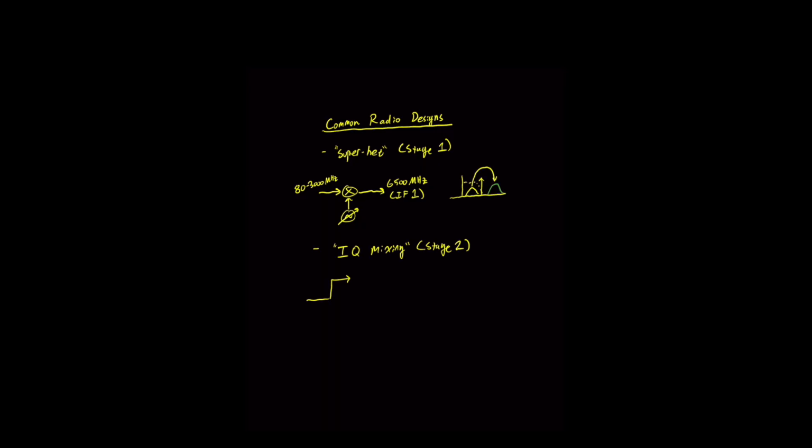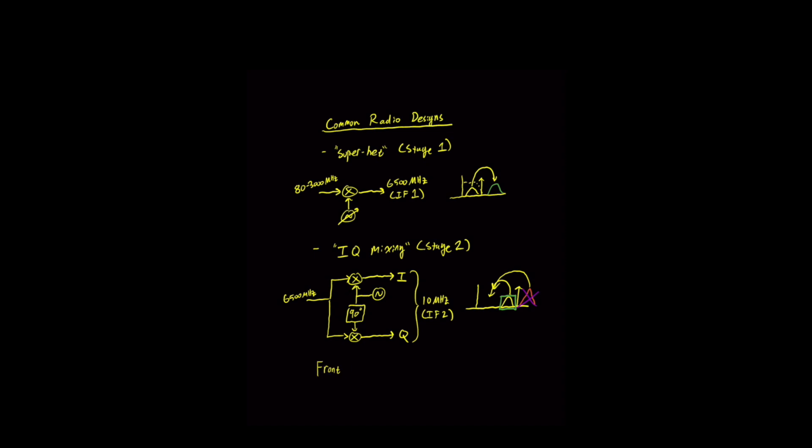Our RF design approach uses a combination of common radio designs to achieve our desired operational range. The final design is a combination of a superheterodyne radio that uses a second mixing stage for in-phase and quadrature digital signal processing to reject unwanted image frequencies. Once the signals are received by the radio front end, we pass them off to the radio back end, which converts the signals into a readable format for the control software.